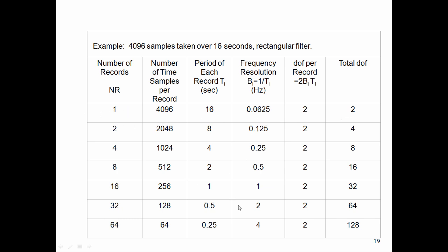So the answer is it just really all depends. Are we trying to identify spectral peaks that are narrowband or sinusoidal peaks superimposed on broadband random vibration? Or do we have something like white noise or some broadband shaker table type vibration? It all depends. What if we have measured field data?